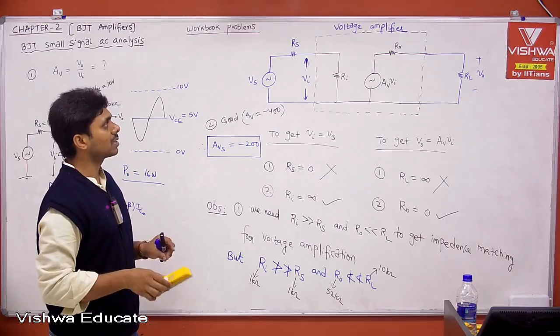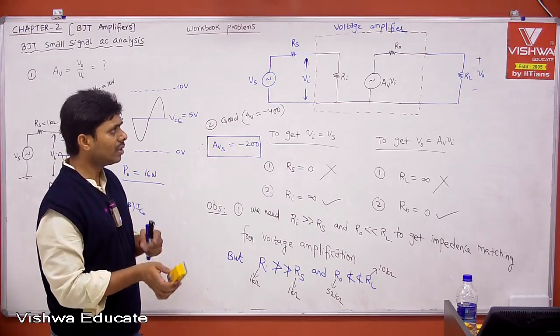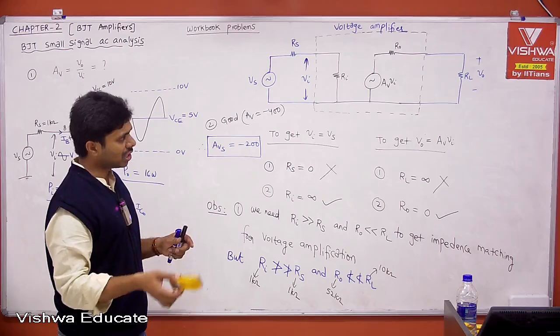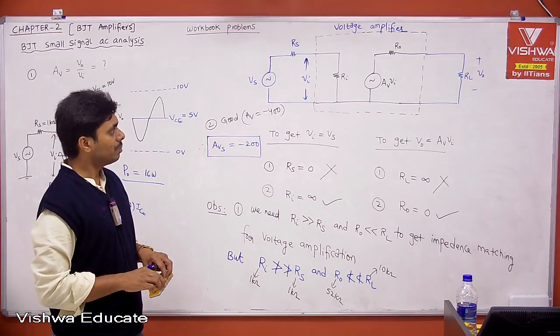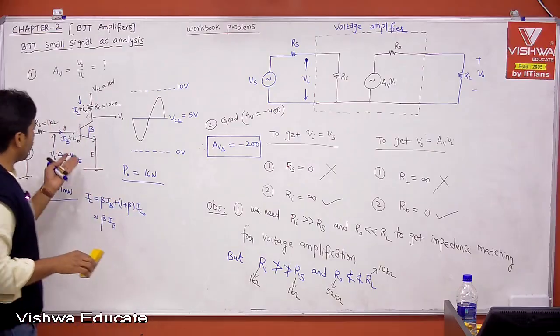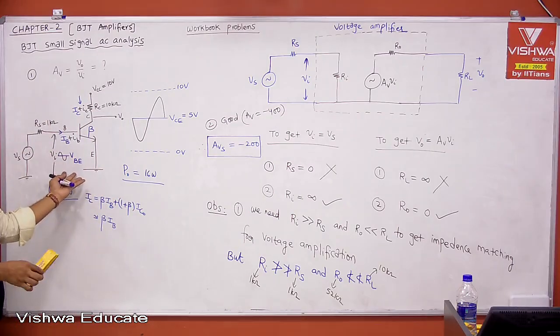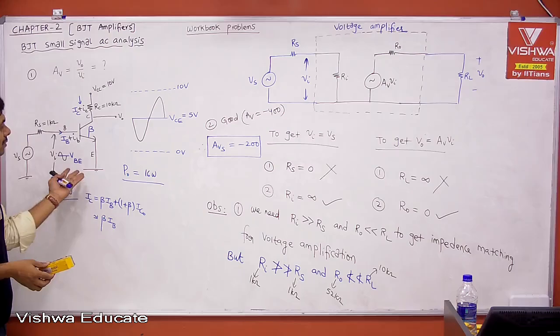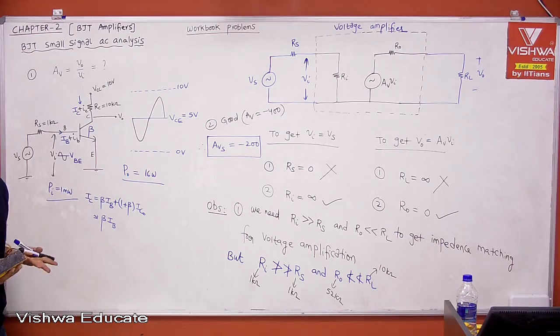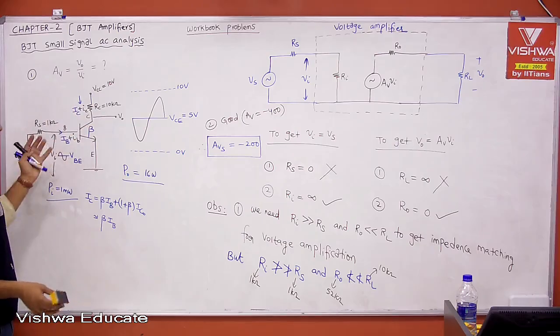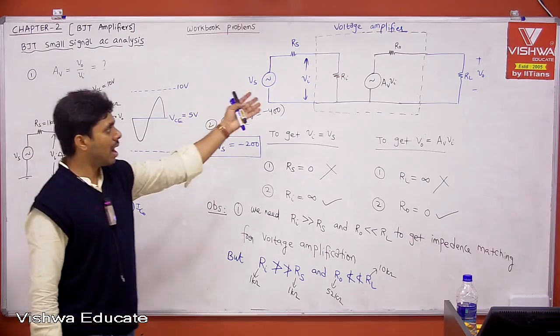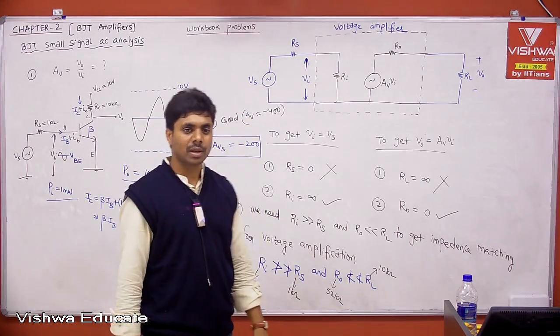Therefore, it takes time, but as we continue it will be faster. One more point: now we understood the advantage of the common emitter amplifier, which is very good voltage gain and very good current gain, but we are not able to utilize it. That itself is the limitation, because of not having proper impedance matching, which is Ri and R0. Okay, let me stop now.